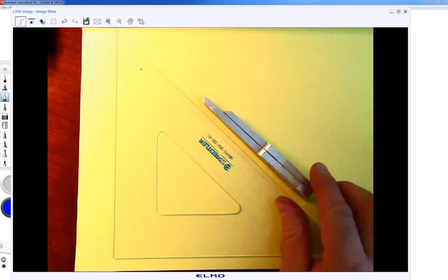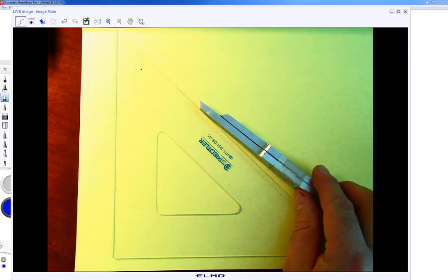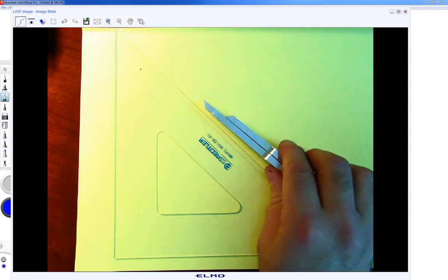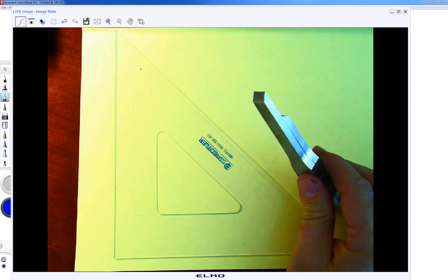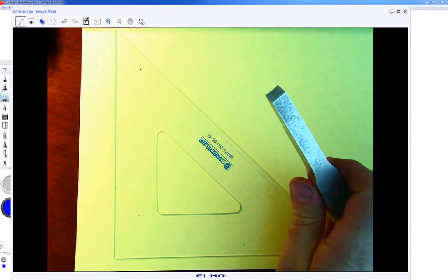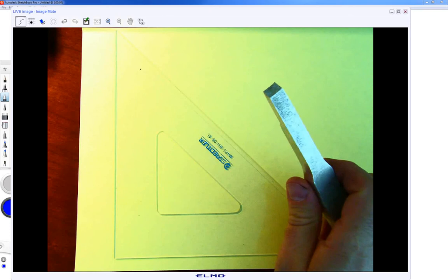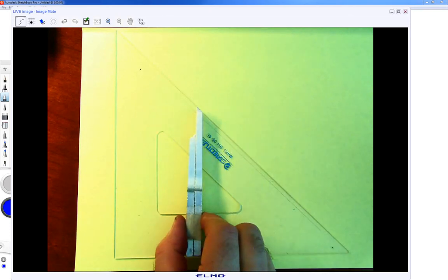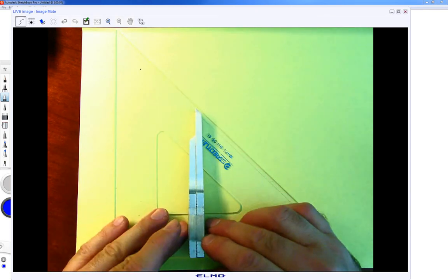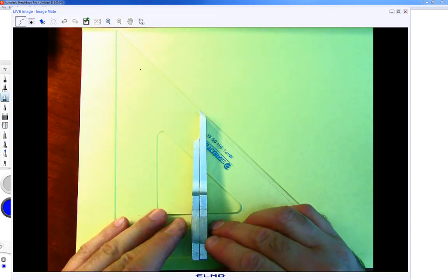This is a very ductile aluminum, and I just taped the two ends together. And let's see if I can angle this. You can see the failure surface there in the image. But what I'm going to do is align the bottom of my specimen with the bottom of the triangle, and we're going to see how close to 45 degrees we can get with that failure surface. And look at that. That's worth zooming in on.